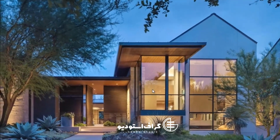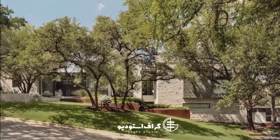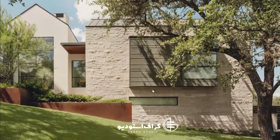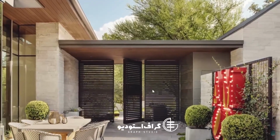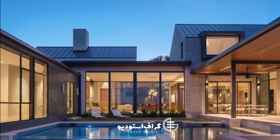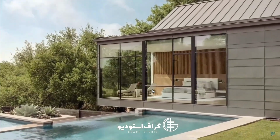The pillow to which we didn't assign a scanline material or fix the normal map, look how it is. It's awful and practically unusable. So we must be careful to edit them if they have problems. I select it and assign the material. I delete the unnecessary parts. Look, I want this one, and we want these two. Let these belong to another pair. And we continue the process this way.